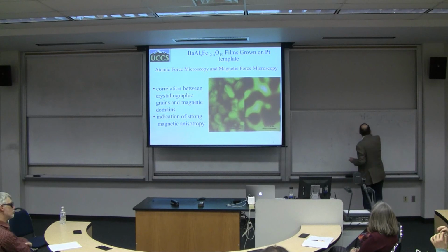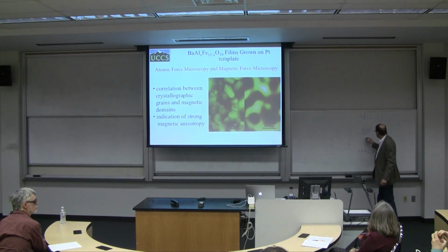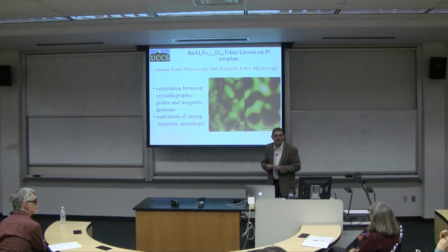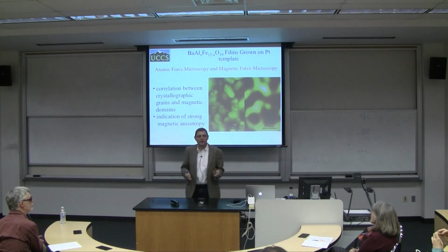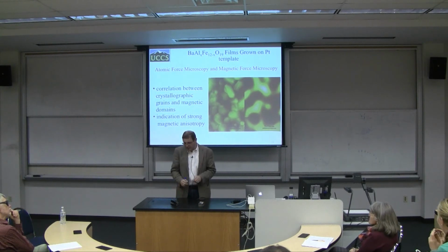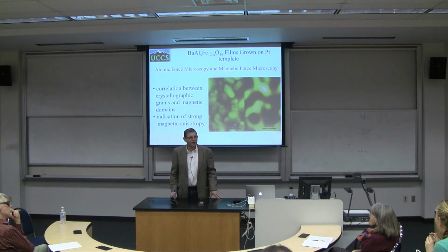And the anisotropy field in these materials nowadays, in modern products, is on the order of 5 kilo-Oersted. So in other words, 0.5 Tesla. It's starting to be a big problem, not to read information, but to write it. Because imagine you have to deliver a pulse of field to a region which is maybe 10 nanometers by 20, on the order of half a Tesla.